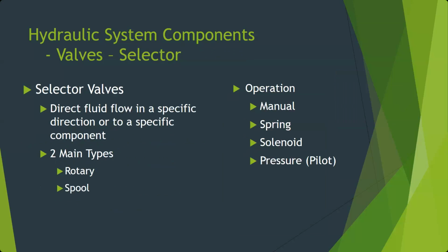Have you done a manual valve somewhere on an aircraft that we've been working on in lab? Anyone operated a manual hydraulic valve? What's that? The tail stairs. The valve for the air stairs on the 727 is a manual valve, okay? Now, that's probably not very common. You won't see very many of those. Anything else we've done with hydraulics has been operated some other way, right?